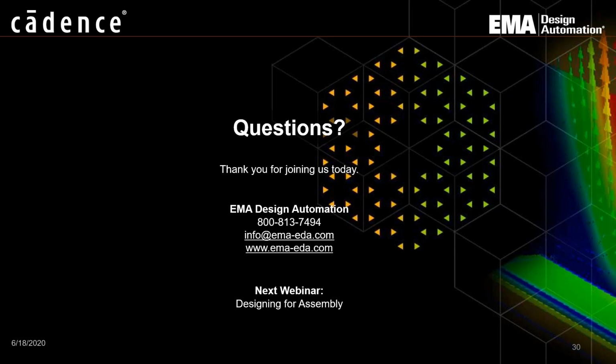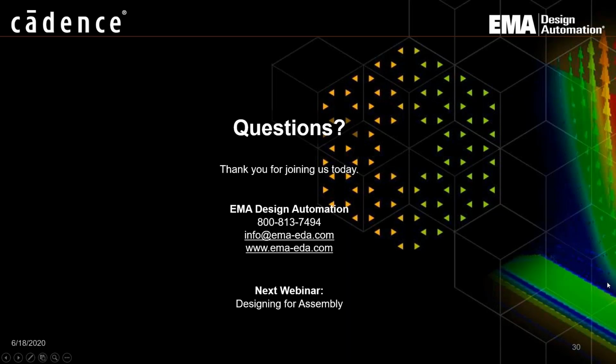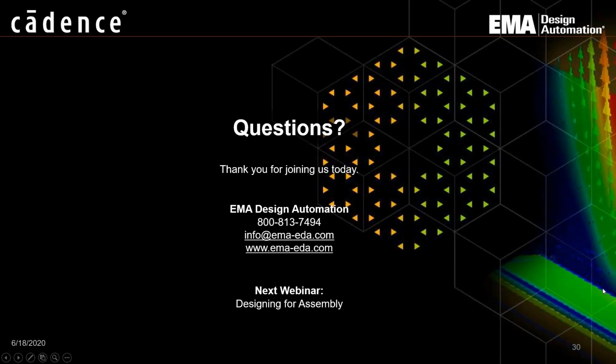Let's see what else we have. For the chips with thermal pads, which model among package, PCB or system is used? Chip with thermal pad. So the thermal pad is under the chip. If it's a true 3D illustration, then we could resolve that. If it's a thermal resistance number, we could also include that. So basically, it could be simplified or modeled as one single thermal resistance, or if it has 3D structures, we could directly simulate that.